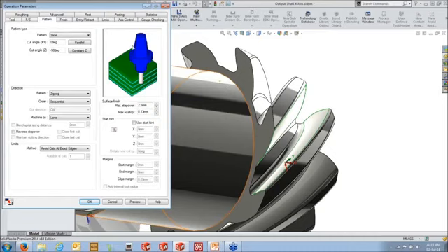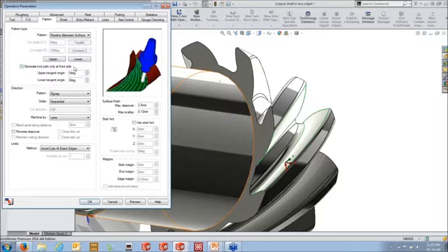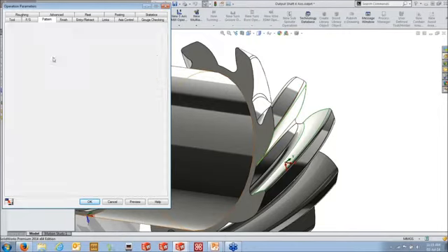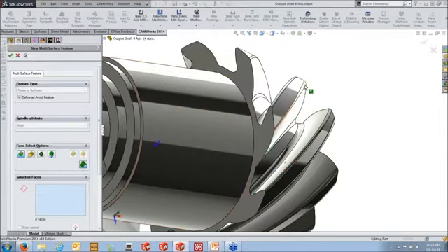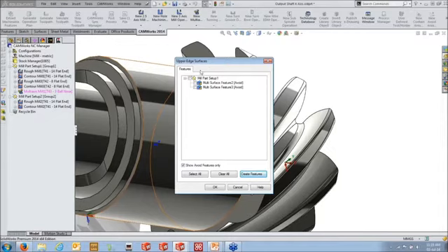But as far as the actual patterning goes, if we're going to rough this out, I typically use the flow line between surfaces for this particular one here, and we define those using upper and lower geometry. So we're using basically the top to bottom approach. So we're just driving the toolpath from the upper face here down to the bottom face, and we'll just create some features that represent, say, the upper pieces of geometry here. And I'll also go and create the lower ones here while I've also got this tool open. So this is the upper edge surfaces, so we want to use the first one. We'll click OK, and then we'll define our lower edge surface as the second one. The bottom radius is down here.